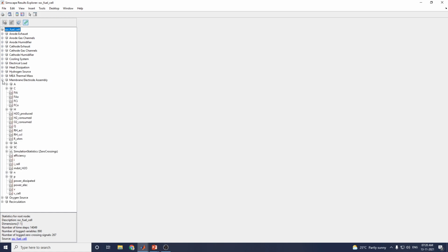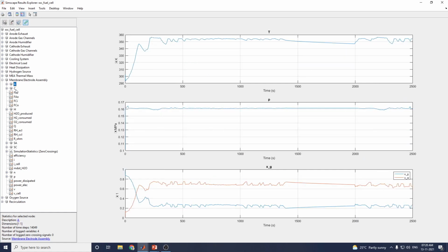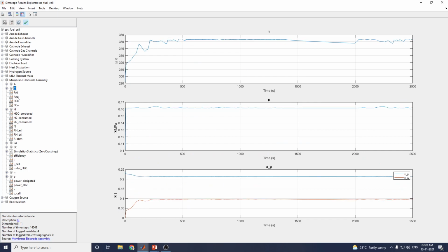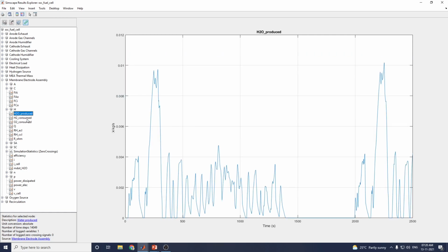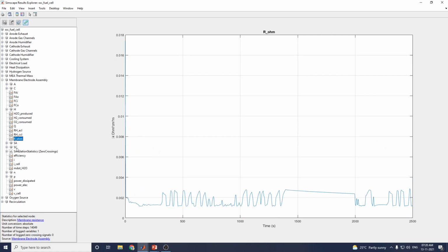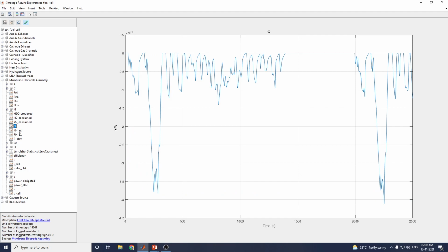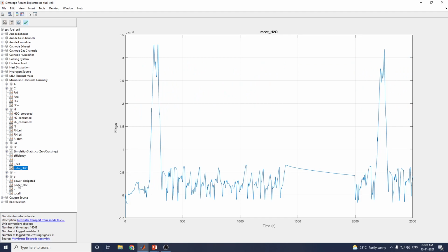Now you can see the membrane electrode assembly. Here in this membrane electrode assembly, you can see how much hydrogen is produced, hydrogen consumed, and current, anode and current temperature, pressure. Also, for each and every block you can see the output in terms of the legends, how much hydrogen is produced and consumed, and in this manner you can see how much losses there are by using the ohmic resistance and electrode losses. Here also you can analyze this output.